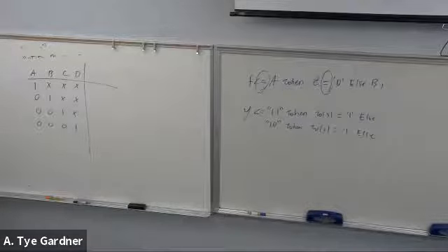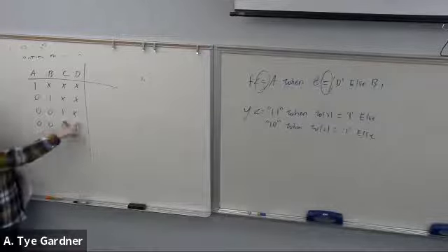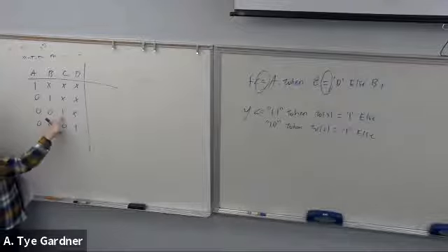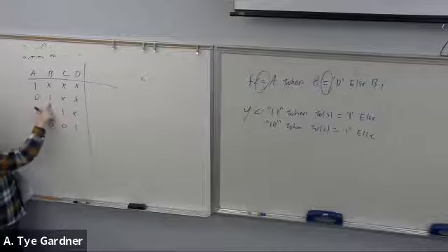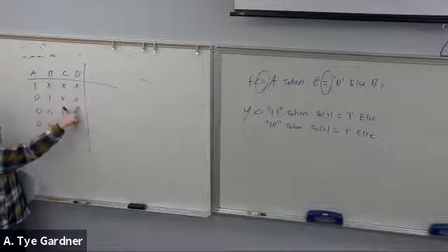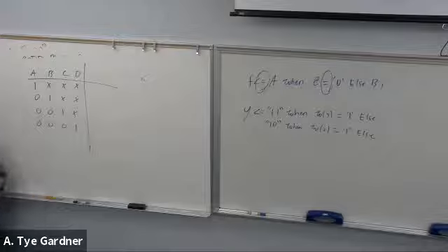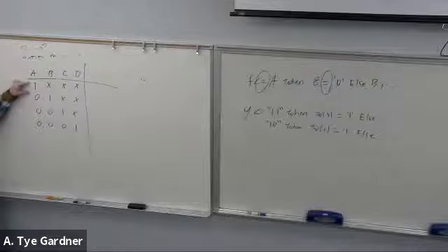So it's very abbreviated because the inputs have don't cares, right? So what it's saying is this is multiple rows of the truth table because this is 0, 0, 1, 1 and 0, 0, 1, 0. This is 0, 1, 0, 0, 0, 1, 0, 1, 0, 1, 1, right? So they represent multiple lines because I don't care what happens to the inputs as long as I know where the first one is. Where is the most significant one? That's what a priority encoder does.